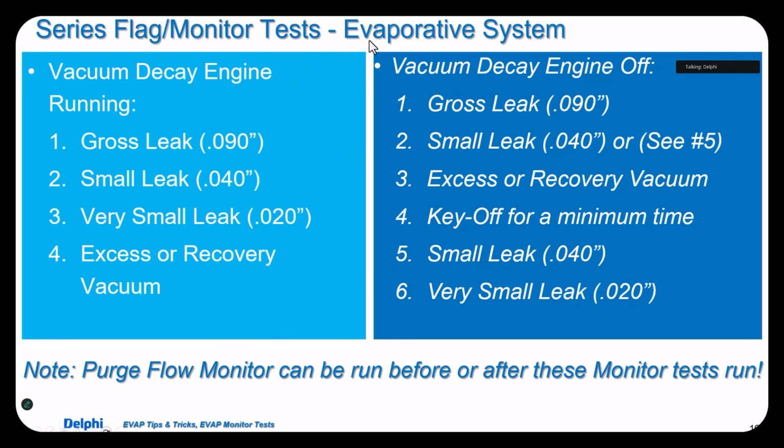I didn't explain parallel, but parallel basically means, for you out there who ever seen the catalytic converter run complete before the O2 completed, that's what we call a parallel monitor. 99% of my time doing this, every time the cat has run first, 99% of the time, the O2 will finish second. That's a whole explanation of that, but the point being here is we're dealing with series monitors, which means we've got to run them all for the flag to flip to complete.